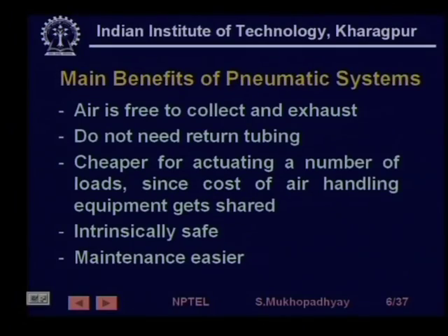On the other hand, there are disadvantages of pneumatic systems as well. For example, firstly, these systems are slower in performance compared to hydraulics. Their power handling ratings are also generally lower, and in terms of sophisticated controls, they are inferior to electric controls.